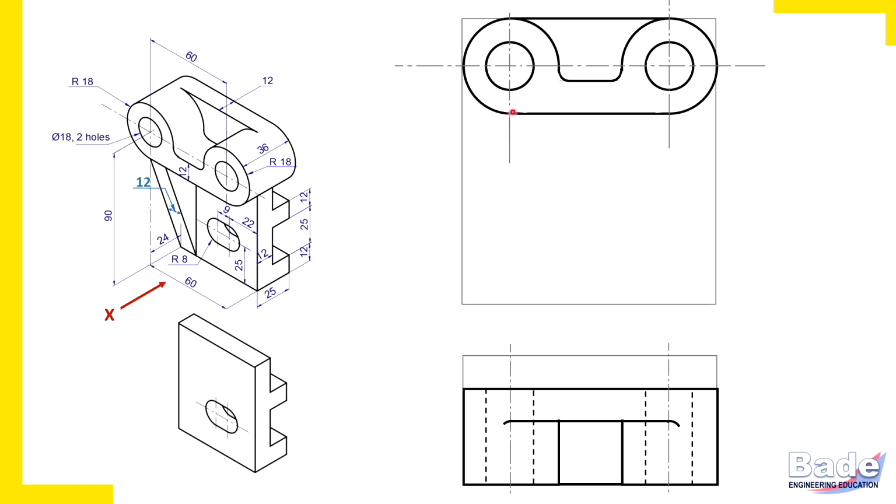Of course, you need not measure that 72 mm. From the extreme bottom to the upper portion, you can draw those lines. And the length of this, in the sense parallel to the length dimension of this object, is 60 mm. So 60 mm length and 72 mm height. This portion is complete. When you measure 72 mm, the part will get connected with the upper portion. So this rectangle is the front view of this portion. But of course not yet complete. We have just measured height and length. In the top view, the same portion will come.